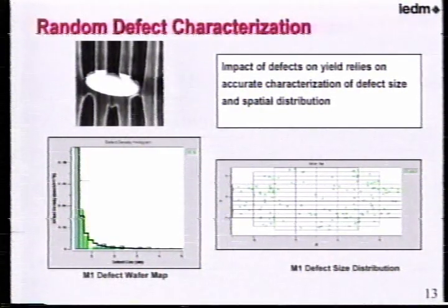Again, it's very important to mention here that as we go backwards, that is, as we go into the regime where smaller and smaller defects impact you more, it's becoming tougher and tougher for the inspection equipment to physically measure and accurately characterize them. And the kill ratios, that is the correlation between a fault or a failure and the physical defect that you observe, become worse and worse. So you often have to resort to electrical defect characterization. And when we talk about the test chips or the characterization monitors, I will show you the kinds of structures that you require in order to make sure that you're electrically characterizing the defect density, which correlates pretty well with the faults.